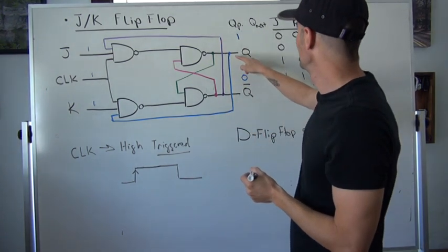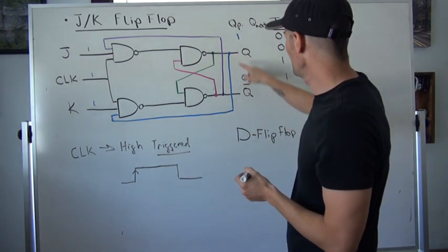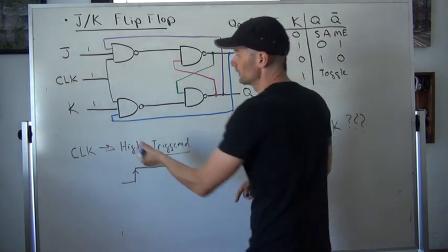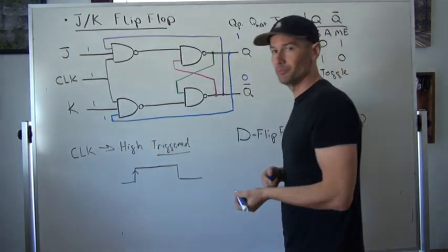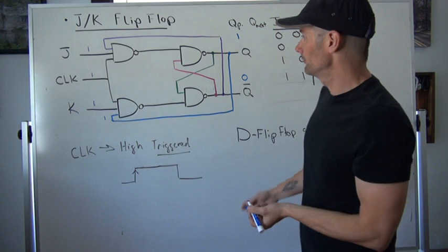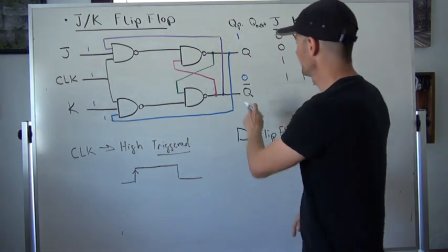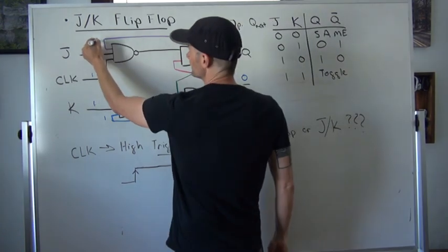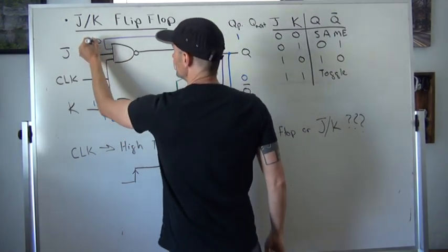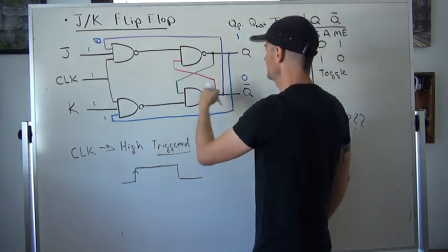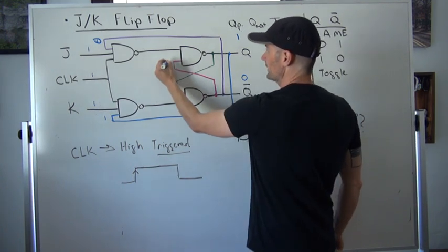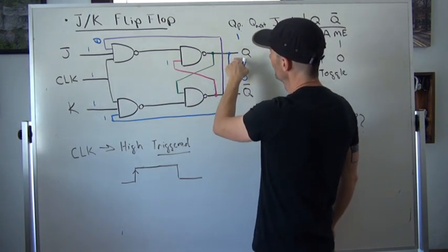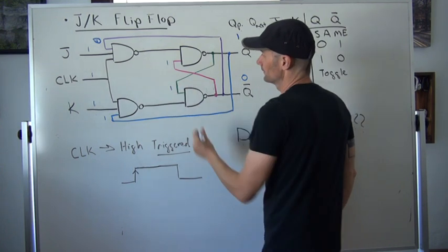So here Q is 1, and so that gets the input in the front to be 1, 1, and 1. Then here we're going to take 0, and we're going to utilize that up here as our input of 0 for the top NAND gate. 0 is fed to here, and then also 1 is fed down to here.